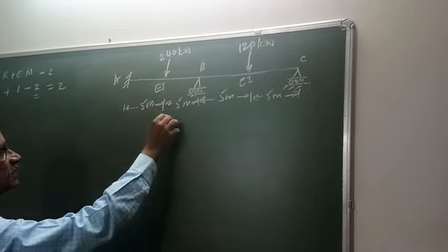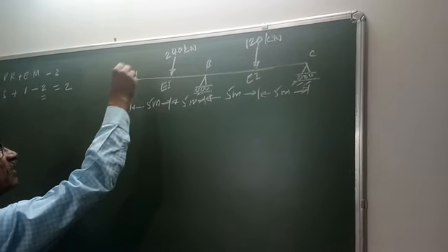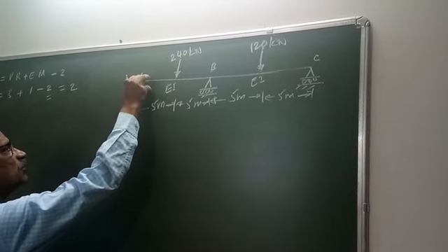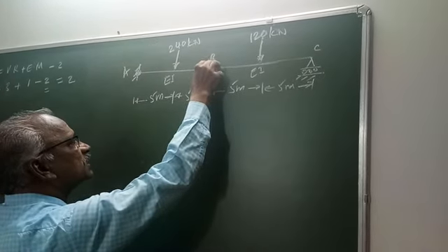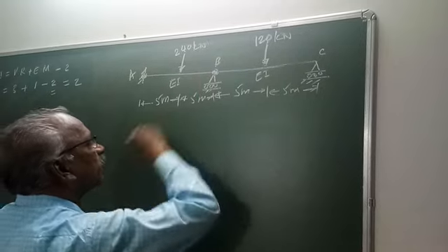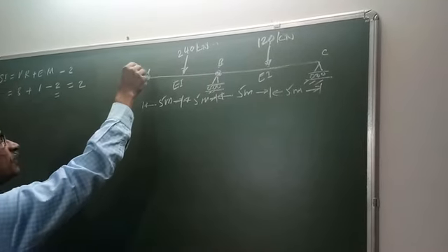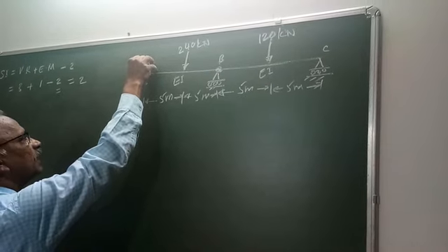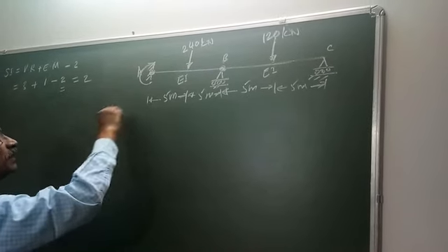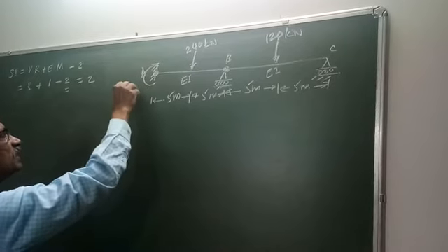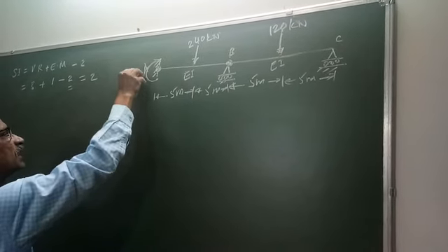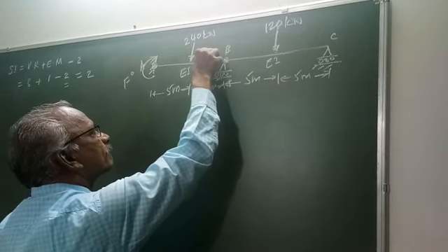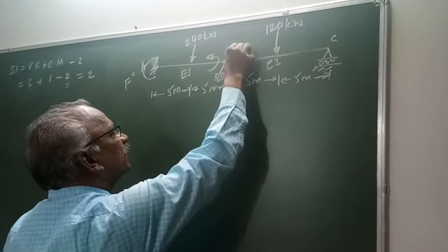This is the given structure. The given structure will be made as a primary structure by introducing 2 hinges at A and B. Therefore, we can mark it as clockwise or anti-clockwise. Say this is one redundant. This is F0. Number will fix later. So this is internal moment.